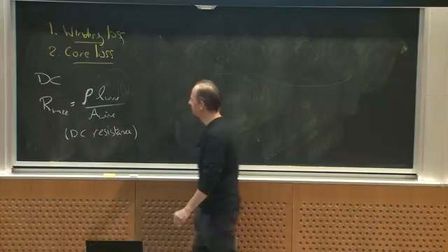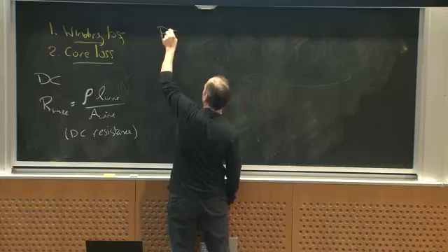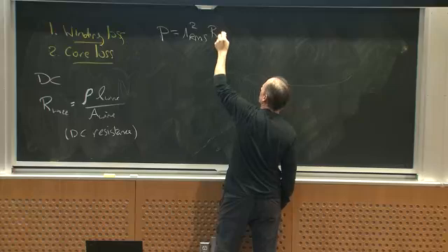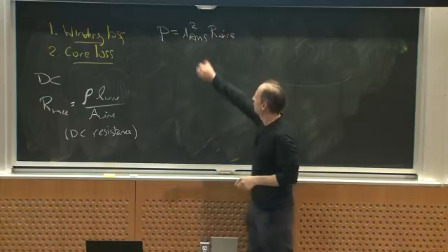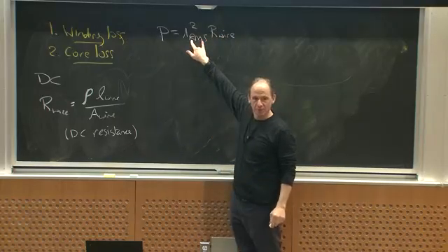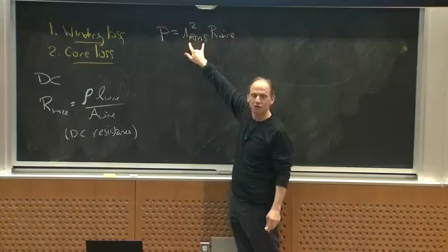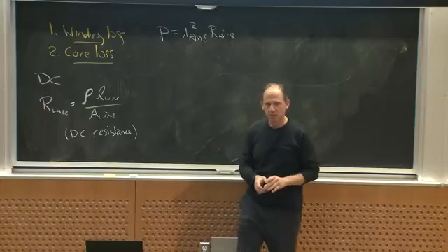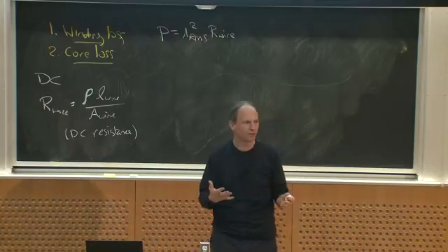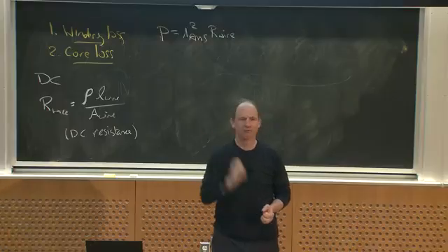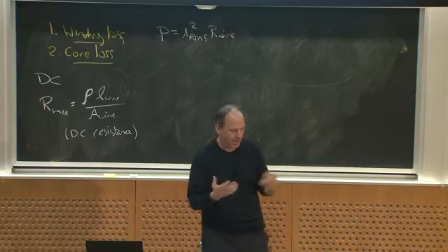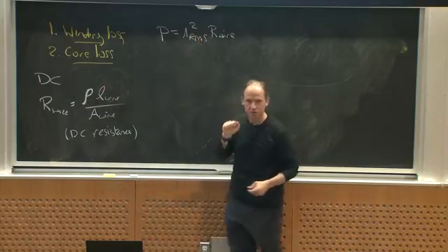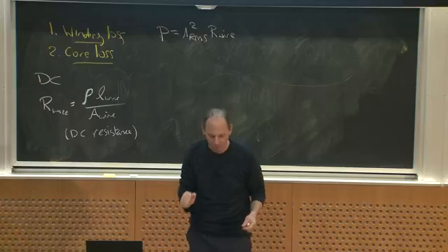Okay, and we'll come back to that, right? Power is just going to be equal to I_RMS squared times R_wire. If the RMS is dominated by the DC component, you have almost a pure DC current, then RMS is close to I_DC, and you might get I_DC squared times R_wire. So it's pretty straightforward to calculate. And so then the trade-off you're making is how fat do you want the wire to be, and how much length of it do you need to get your loss low enough. Okay.